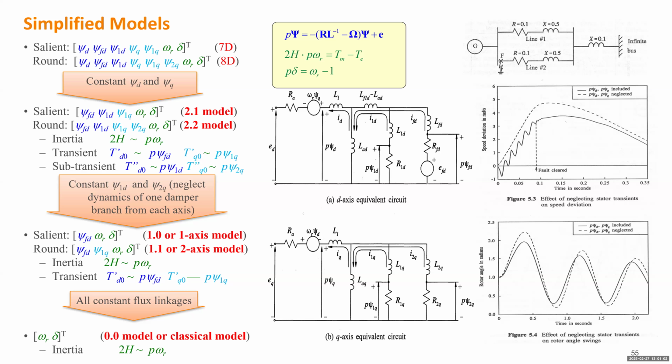Okay, so in some other fields, where they study protection or the design of generators, they definitely can model the generator more accurately. Similar to what we derived based on the voltage equation and flux linkage equation, you can always go back to those equations. If you do electromagnetic transient study or simulation, you will need to go back to those equations because the models here are not accurate. Don't use those models for EMT simulation, unless you only want to do an approximate study.